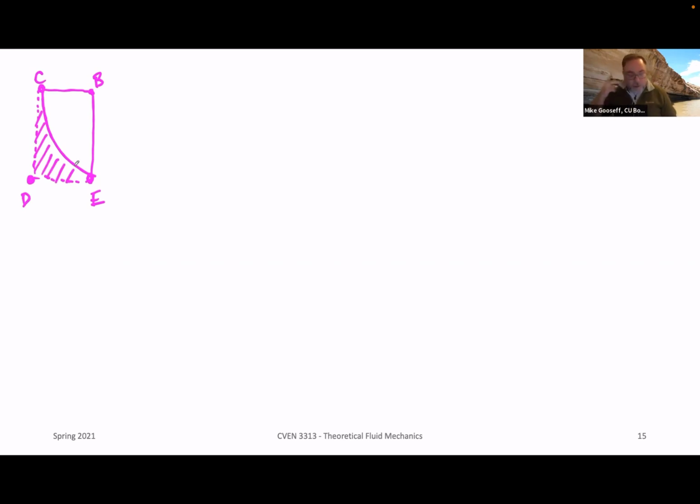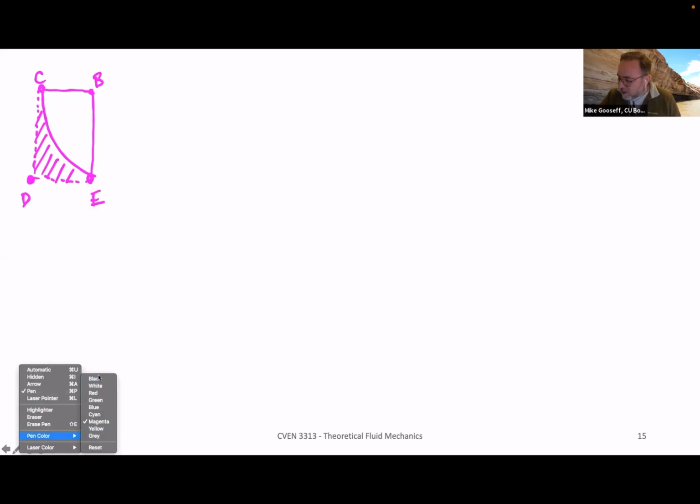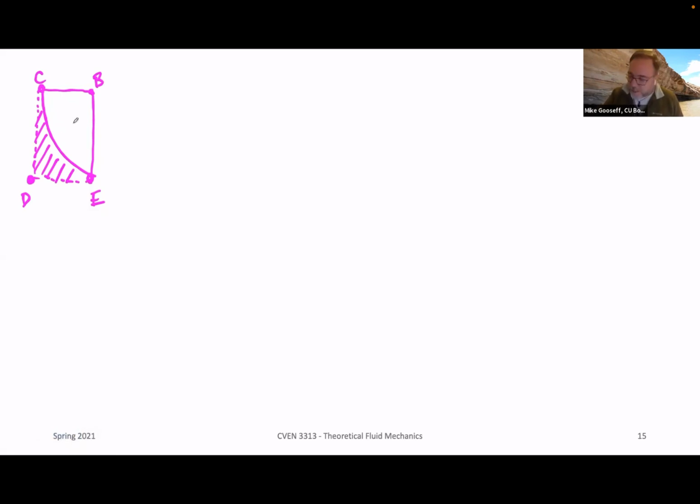All right. So the forces that we're considering here, let me change my pen color. The forces are some FG. I don't know if that's drawn in the right direction or not, but the point I want to make is that it's not perfectly horizontal, it's not perfectly vertical. And we have to deal with these other forces that are coming into play here. Here's an F1 that will be the hydrostatic pressure acting on the left-hand side of this. F2 will be a hydrostatic pressure acting up from the bottom. And then we have the weight of the water in this area acting downward.